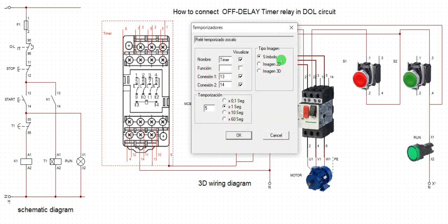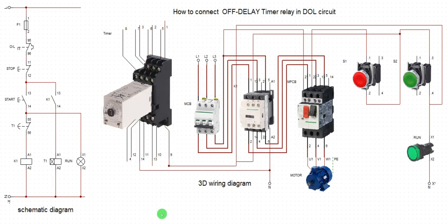Okay, so go back to schematic. All right, so look at terminal 14. Come to my neutral. Look at terminal 13. I will feed terminal 13 from my retainer circuit. Okay, my latching circuit. I have it here already. From my common, I feed the coil. All right, so this one is taken. Take a look at this again. From this latching circuit, I feed the coil. The same way, look at my latching circuit. This 14, 13 is the latching circuit of this contactor. So I feed the coil of this relay from that latching branch.